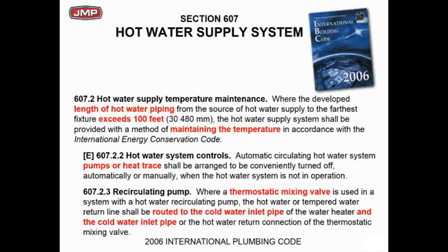So let's look a little bit at what we got on hot water circulation and what they're recommending to you. This is the old IBC, ICC code that most states are still on. And the point of this one is it did say 100 feet between the point of recirculation and the fixture. The 2012 code, some states adopt that. Remember, states are slow getting there. It shows 50 feet. Your local plumbing code may show a different number, so you need to check your local plumbing code and go for good design. Good design might be 50 feet, but you need to verify that for your firm. I hope you understand the point.